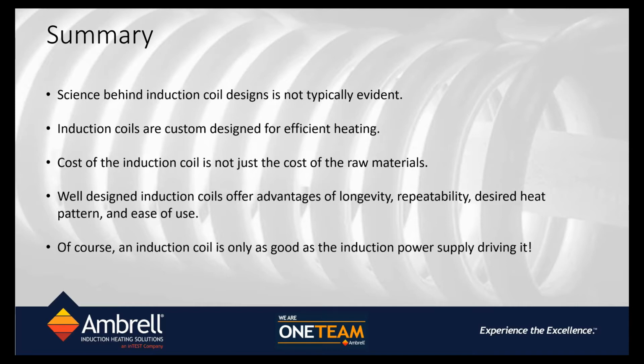Then figure out how much energy was used in that heat cycle from the wall. The difference in the energies is going to give you the energy that is consumed inside the induction heating power supply and the coils. That is going to give you the best possible answer to your question.